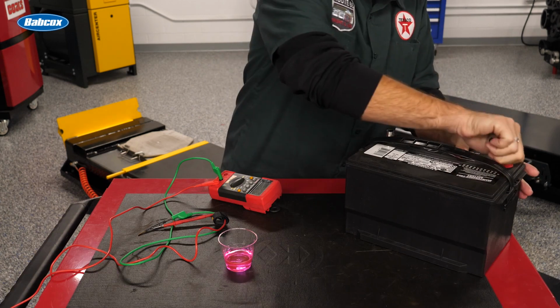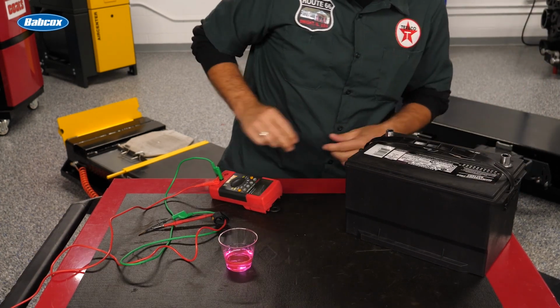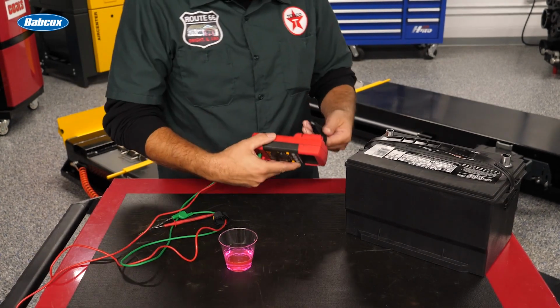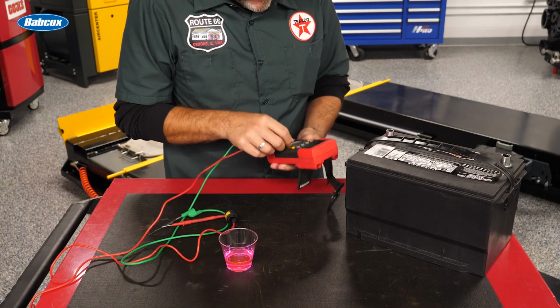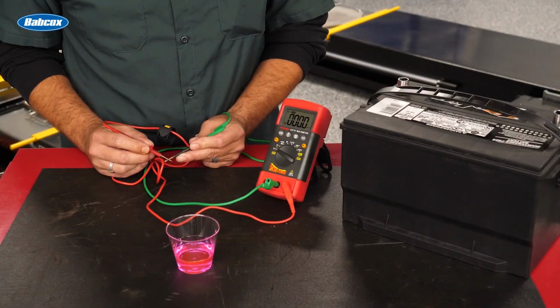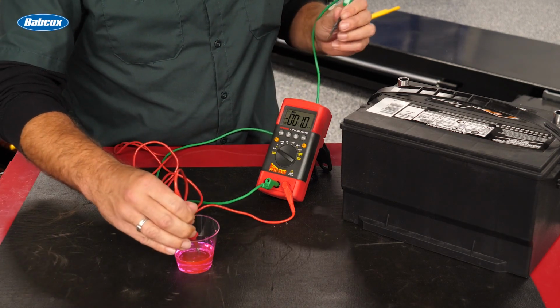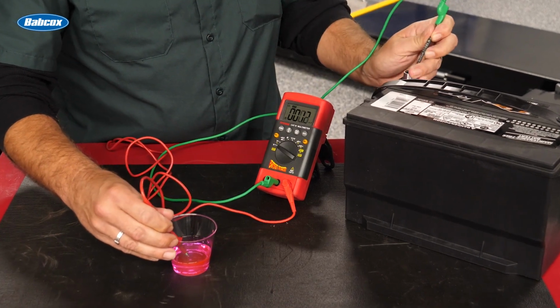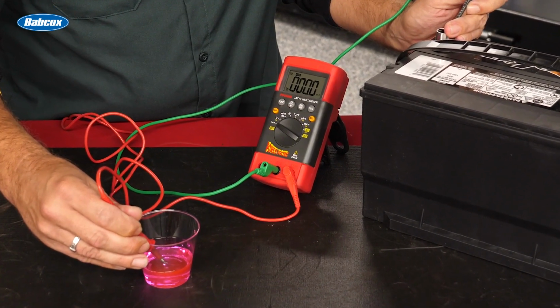Learning to test for electrolysis in the cooling system is an important skill. You can check for voltage in the cooling system by removing both cables from the battery and ensuring they don't contact each other or the vehicle, then touching the negative contact of a voltmeter to the battery ground or a known good ground, and suspend the positive lead in the coolant, making sure it's in contact with the coolant, but not touching any metal part of the radiator or cooling system.